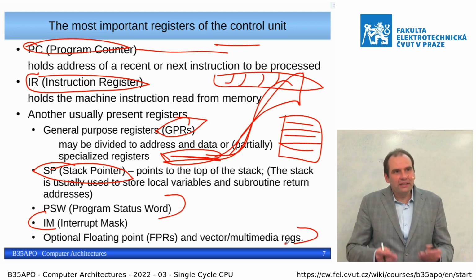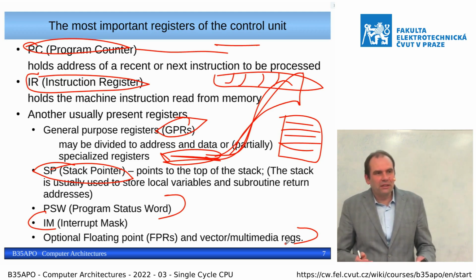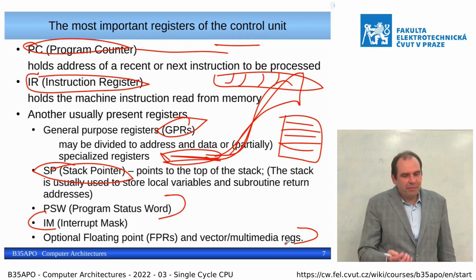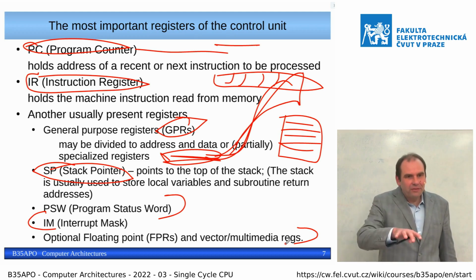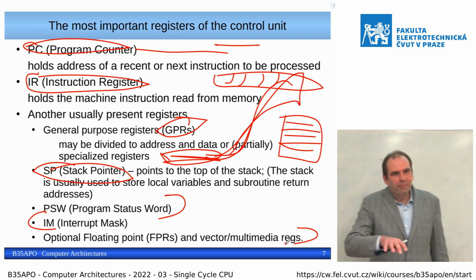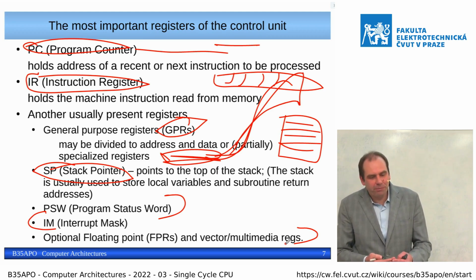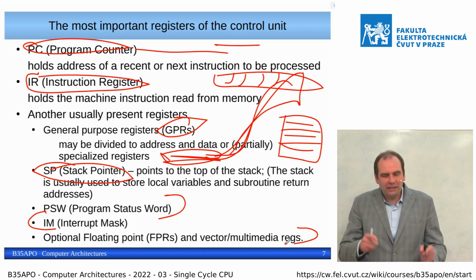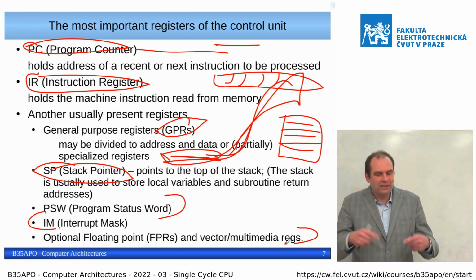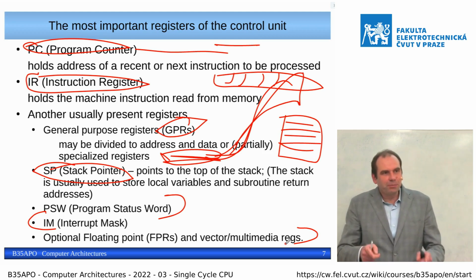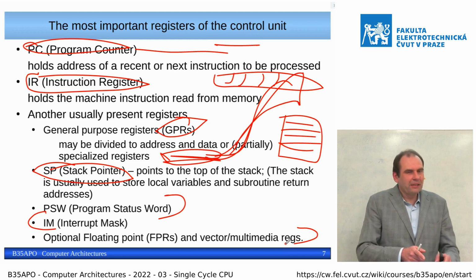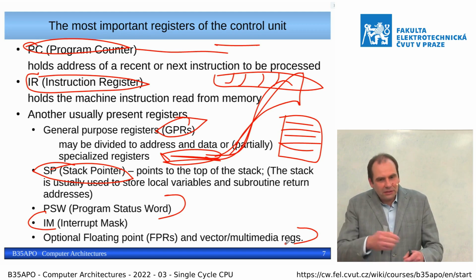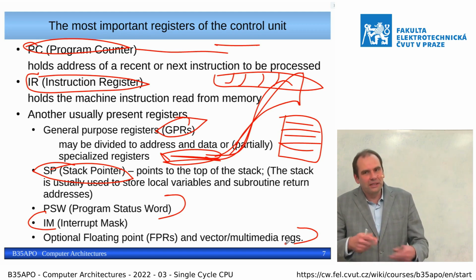As we have said, data in the memory are some combination of ones and zeros, and basically it only depends on their interpretation, which glasses we use and put over those data. But if those glasses correspond to the actual architecture of the processor, so basically if we work with signed and unsigned 32-bit integers and the CPU has a 32-bit machine word, then such processing is easy. If you have only an 8-bit CPU and want to work with 32-bit data, then you need a list of instructions which reads the individual bytes and proceeds with the operation.